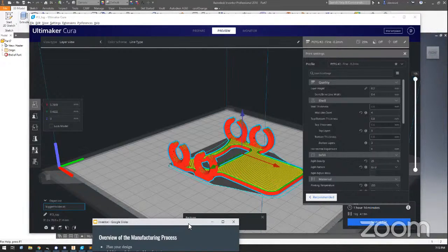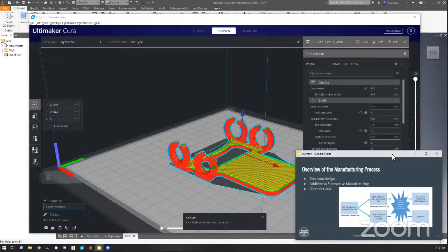The second is subtractive, and that's the kind of machine like a lathe or a mill that uses some kind of cutter that removes material from a piece of aluminum or steel or plastic. It's actually cutting to remove material. So we have additive versus subtractive manufacturing.